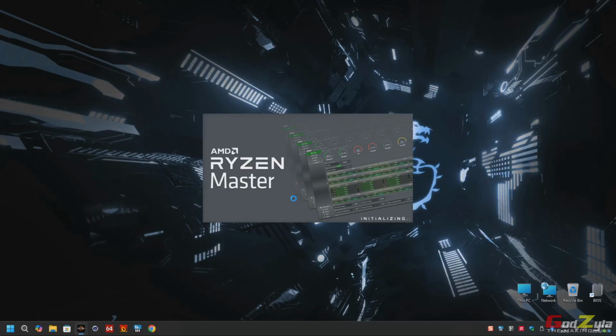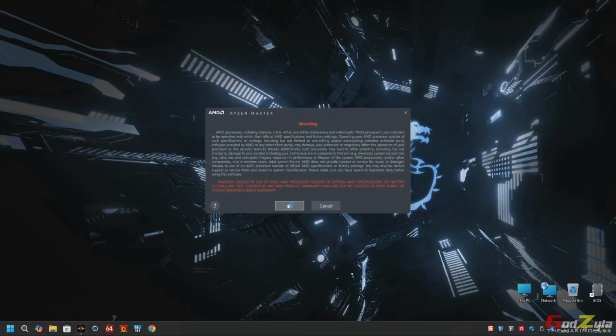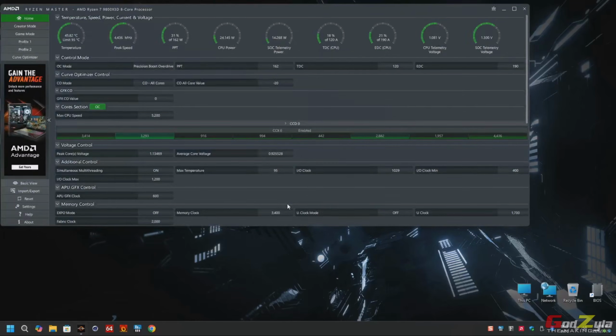Okay, let me just load Ryzen Master. Hopefully it will pick up. Okay, great. Take a look. The SoC voltage is 1.3. It's already above 1.2. So unknowingly, let's say you configure like what other YouTubers have been telling you, set to motherboard and such, and you just run the Expo profile without noticing this, and your RAM is running at 1.3. Okay, anything above 6400 bus speed,